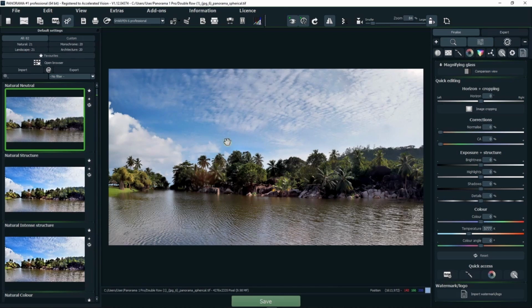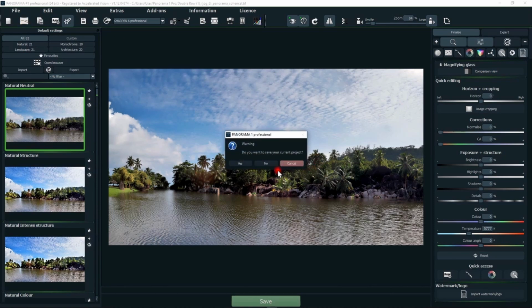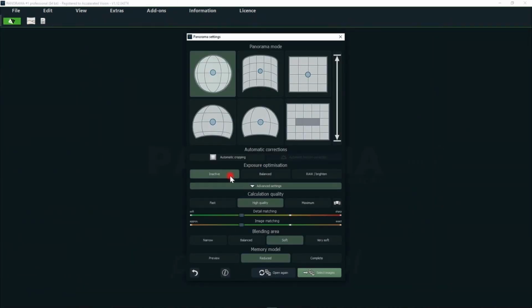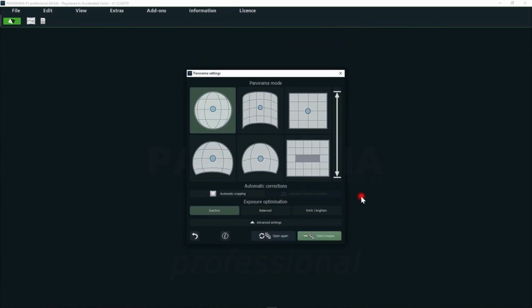Now, there's one more thing I want to show you. To do that, let's go back to the panorama area and close the advanced settings. Let's reset everything down here on the left to the default values with the back arrow. Now I'd like to draw your attention to this button over on the right. At first glance, it looks a bit like an up and down scroll bar, but this is our vertical mode, the portrait mode for panoramas, which switches the program over internally. If we turn it on, the planar mode turns off. That doesn't work with vertical mode.